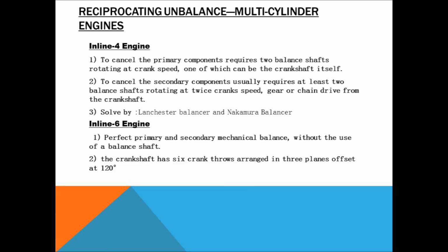And finally, I'm going to talk about the reciprocating unbalanced multi-cylinder engine. There are basically 2 types, the inline 4 engine and also the inline 6 engine, which we are going to compare as below. The inline 4 engine has primary and secondary components.